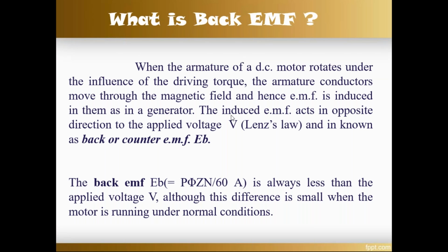Now that induced EMF acts in the opposite direction to the applied voltage, and this principle is given by Lenz's law. Lenz's law says that the cause, the output, opposes the input. It is known as back EMF or counter EMF. Sometimes they will ask for counter EMF, sometimes they will ask for back EMF.